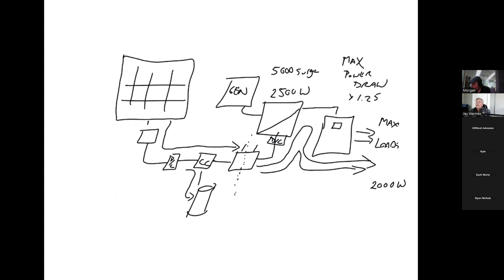So the inverters here will say it's a 2,500 watt continuous with a 5,000 or a 4,000 surge. And usually in a household, having double for the surge is plenty. But if you're setting up a system where you're only operating heavy equipment, like let's say in a barn where you're running milking machines or something like that, you might want to put in a much bigger inverter just because that surge capacity might need to be bigger.